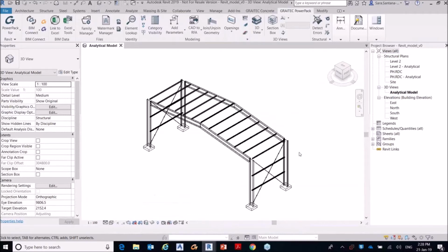Now, as Sarah mentioned, at this stage in the project, you might want to update your Revit model, or you might want to just send your model to Advanced Steel to take your model to a higher level of detail, add in the connections, any miscellaneous steel, stairs, or railings, as well as number the model and output fabrication drawings. You can output the general arrangement drawings again in Advanced Steel. However, this can be done in Revit, and in order to save time, you might want to split or divide that workload between the departments. So have the general arrangements done in Revit, and then have the fabrication details done in Advanced Steel.